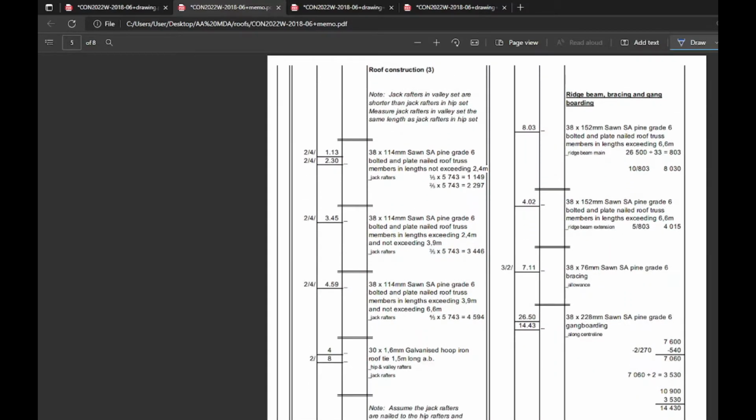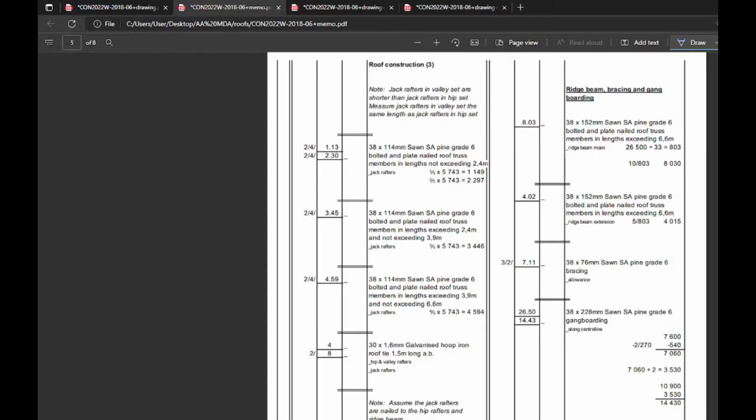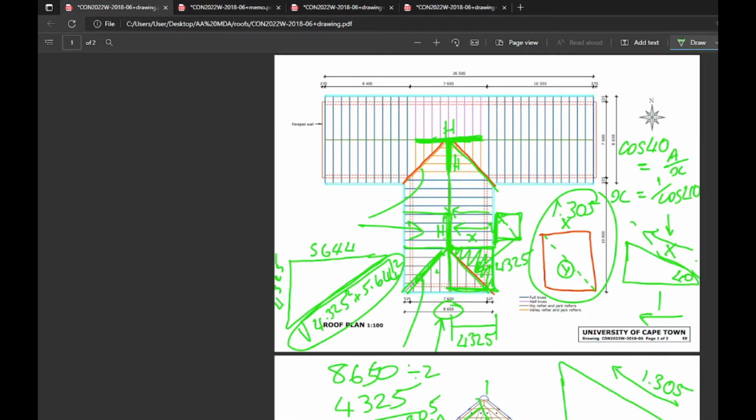It's a tricky section. That is probably the most complicated to get your head around, because you have to visualize that we're first dealing with a square on plan. Okay? Now, we use this gable end, but there's obviously no rafter here. First dealing with a square on plan. You can't do much with a square on plan. You've got to convert it to a value that accounts for the slope. And if you were lazy, you'd not account for the slope and you just do Pythagoras straight.